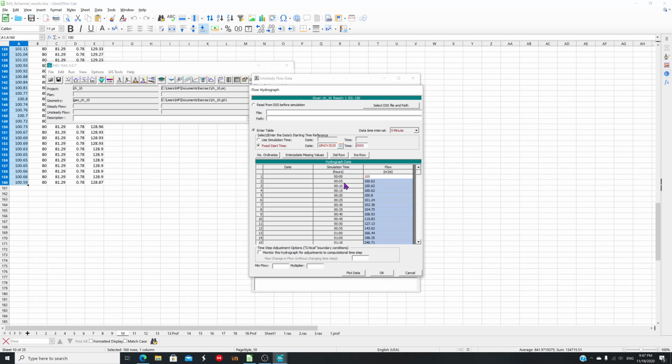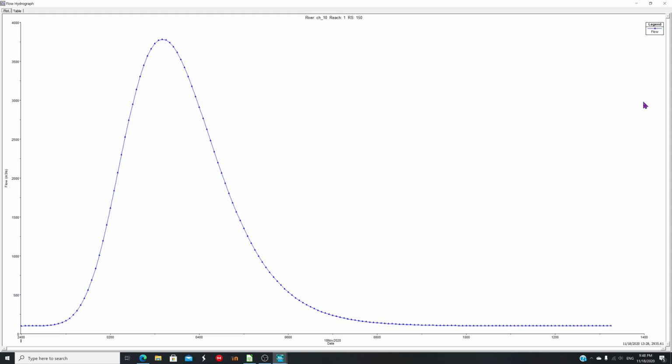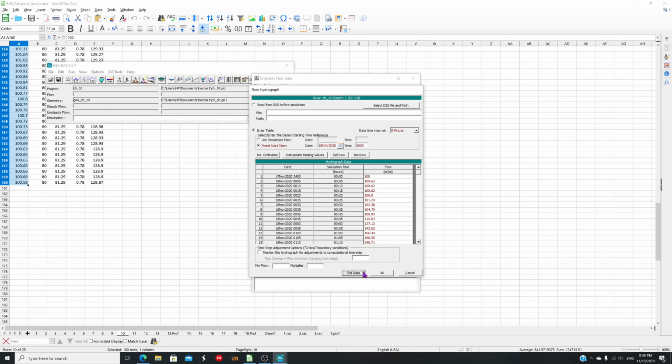Okay, so our inflow hydrograph is this. Beautiful. All right, so what we have just done is we have put this into flow hydrograph on our topmost cross section. Okay, we need to note these dates, start time and end time, because later on we need it.